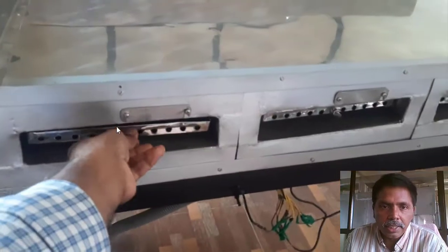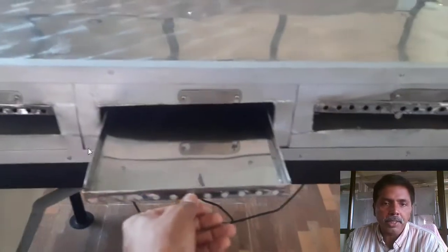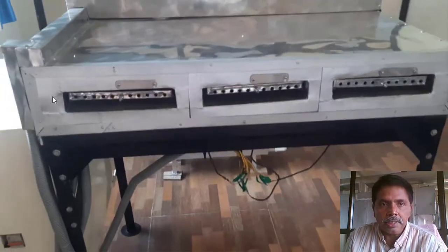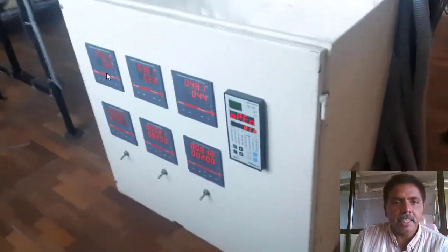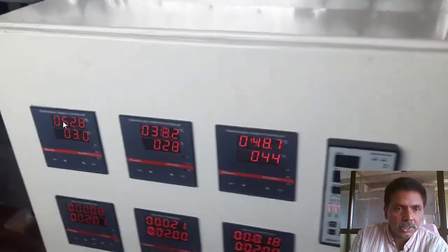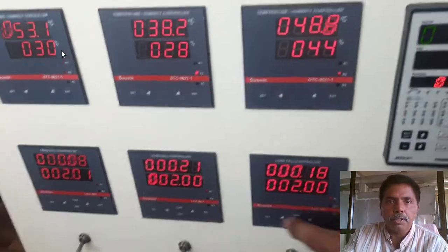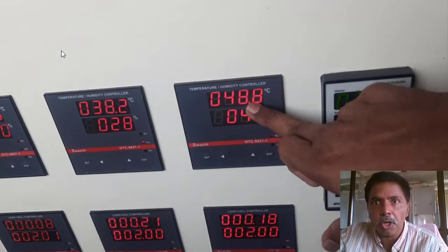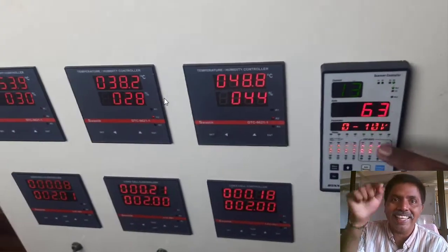Here you can see 3 trays for repeatability of the readings. The loading capacity is maximum 100 grams to 200 grams. And this is the solar dryer, the laboratory setup solar dryer. Here we have connected heater coils and a load cell. We are measuring the relative humidity. You can see this is the relative humidity. Temperature and relative humidity we can set: this much temperature, this much relative humidity of the air. Relative humidity is the moisture content of the air. Why? Because different places have different moisture conditions. So initial temperature and moisture conditions we create artificially.